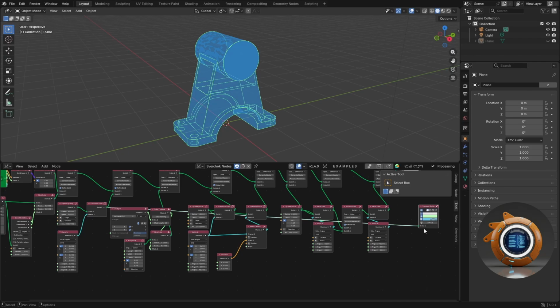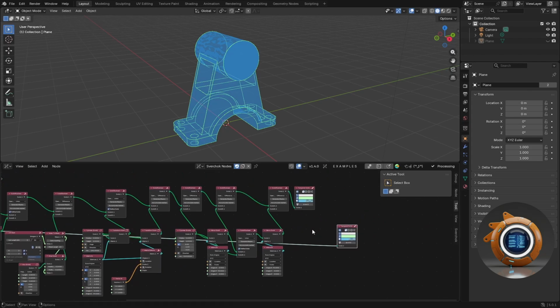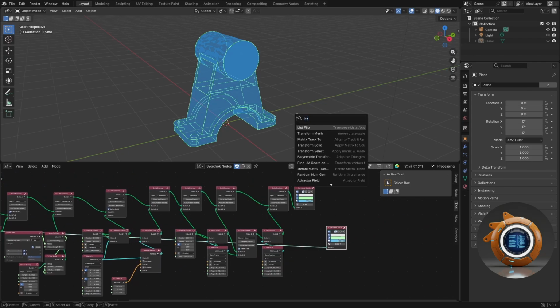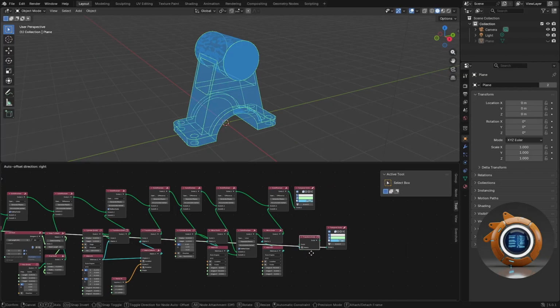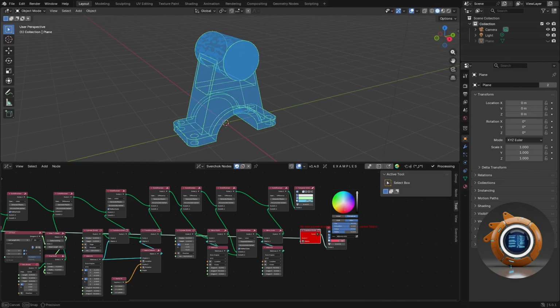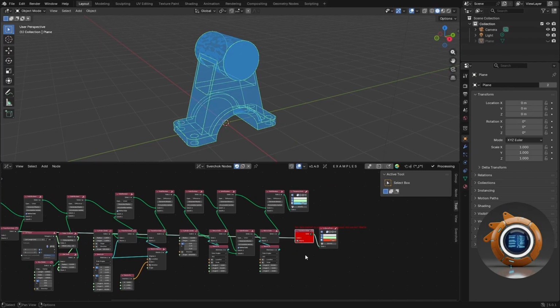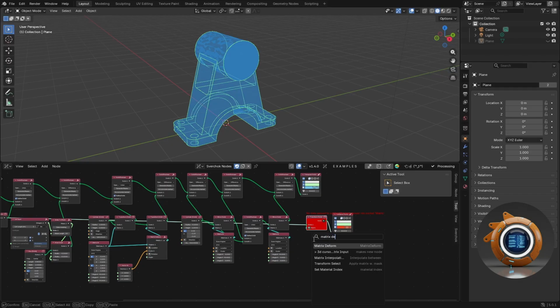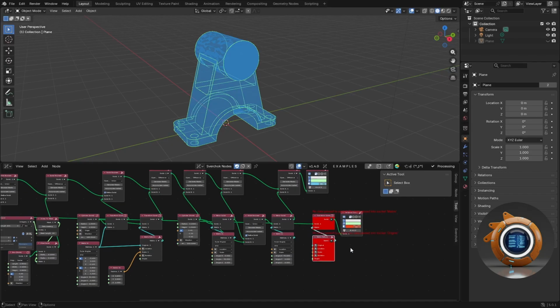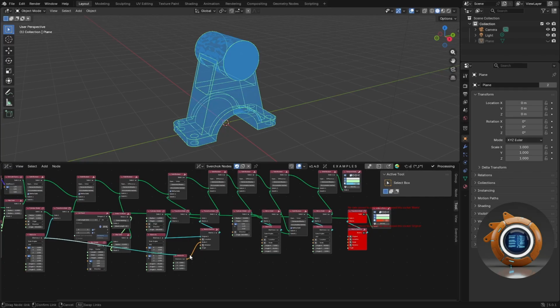I was looking for this cylinder. As I mentioned when I first created it, I knew I would reuse it later to make the hole in the upper part. To do that, I use again the transform solid plus matrix deform method we used before. I simply grab the matrix applied to the first cylinder, plug it into the matrix deform node input, and scale it on the x and y axes.